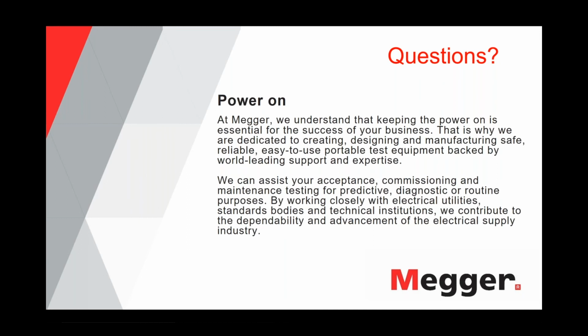But from a practical point of view, if you have high tan delta values, two things to that. Either you have really a very aged insulation, or, and that's always what people check out when they have high tan delta values, they check the terminations, because you can have a high tan delta value with a good insulation, but with a very poor termination, because you have leakage over the termination. So what people do on, let's say, expensive cables, expensive circuits, when they get high tan delta values, they will always first change the terminations and then retest it and see what they get for the true insulation.